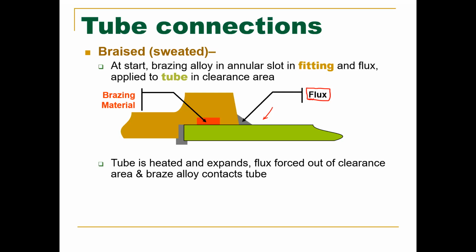All right. So as we apply the solder to it, the flux is flowing, and the solder wants to search for that heat, all right? And it will follow the flux and it will get into all those nooks and crannies, all right? And make a really good seal or a really good electrical connection. That's the job of the flux, all right? Now, this brazing material is the actual solder. It's the weld. It's the actual material that will make that strong connection.